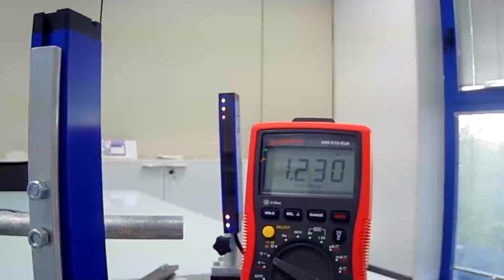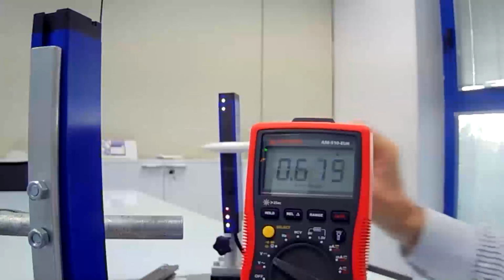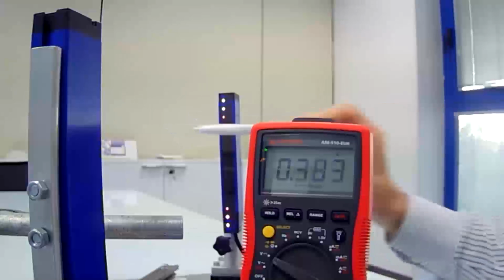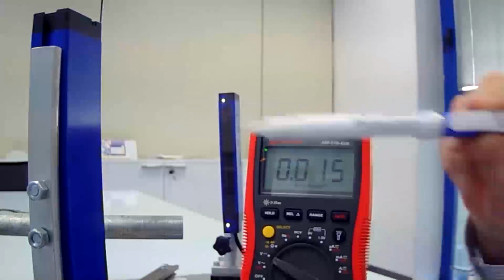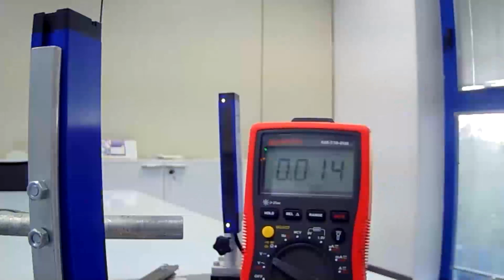So connect the blanking wire to positive and restart the unit, and also in this case, the unit adjusts its sensitivity in a way to work in the correct way. Now you can see that the sensor works without any problem, even if we have a metal part in the middle.